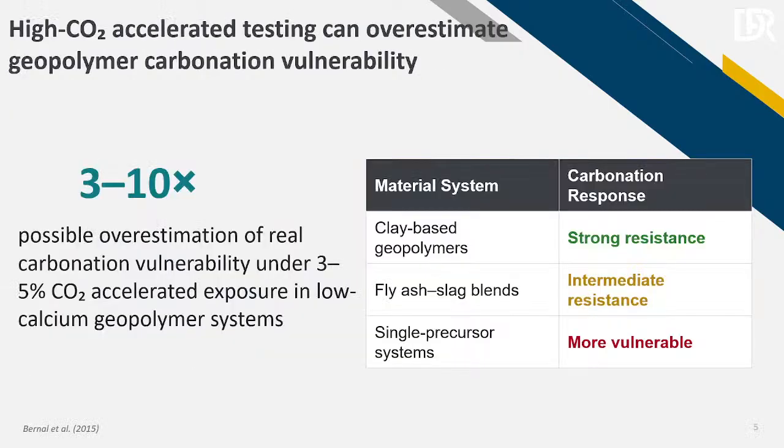But if we want to use the same parameters for geopolymers, then the case will lead to about 3 to 10% variation, or overestimation, for the geopolymer. And that is mainly because geopolymers are not made out of as much calcium as normal concrete is. So the pH level will drop more dramatically when it's exposed to the atmosphere, the CO2. And that will lead to overestimation of the material.